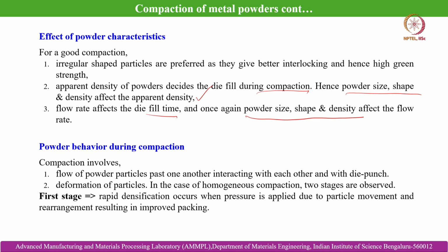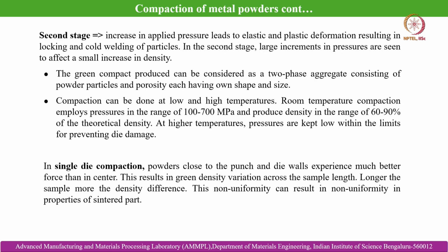Number 2 is deformation of particles. In the case of homogeneous compaction, two stages are observed. In the first stage, rapid densification occurs when pressure is applied, due to particle movement and rearrangement, resulting in improved packing. In the second stage, increase in applied pressure leads to elastic and plastic deformation, resulting in locking and cold welding of the particles.